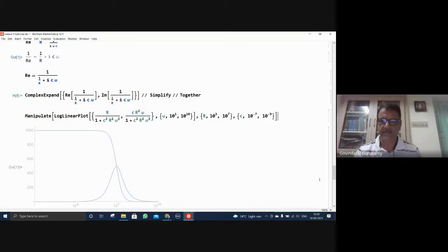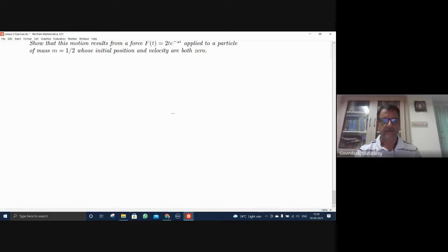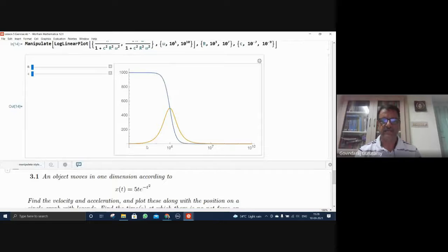It's manipulated now. See, now what is happening in this time constant will be RC, 10 power, how much? 10 power minus 3, no, 10 power minus 4. So which means this peak will go to 4. And when you start entering, the peak will be shifted to 10 power 4. Yes. See? Just come here. Now if I change the R value or a C value, you can see this shift here. Okay? This is the beauty of this.